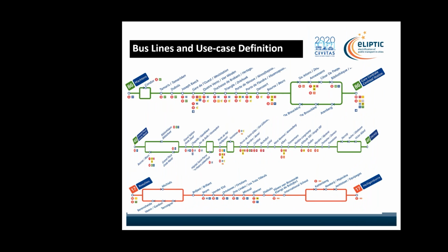And also, the operator is willing to change the route to make more interaction with the new lines planned to be integrated in Brussels. So this is the idea of how we are going to gain from integrating high power charging to the DC network. The DC network is the added value, because otherwise you really need the electrification from the grid to add AC/DC and also a transformer, and then again a DC converter to control the power flow to the battery. So this has the potential to improve the TCO of the system.